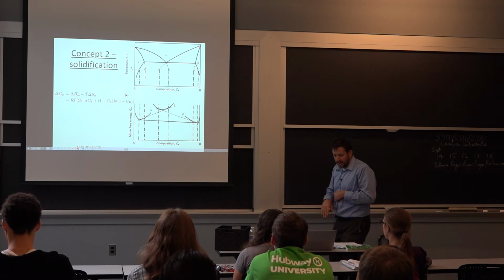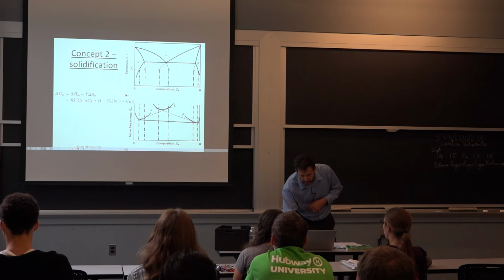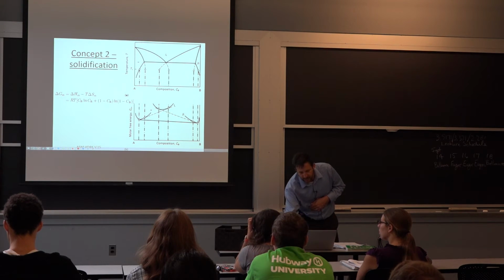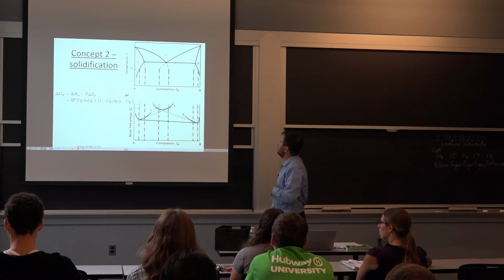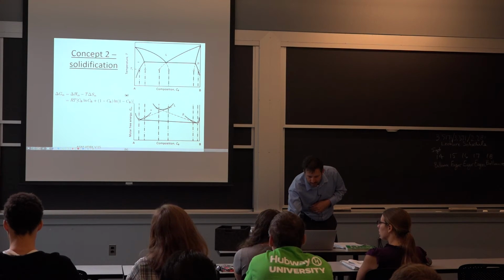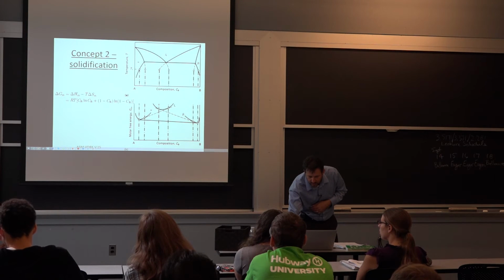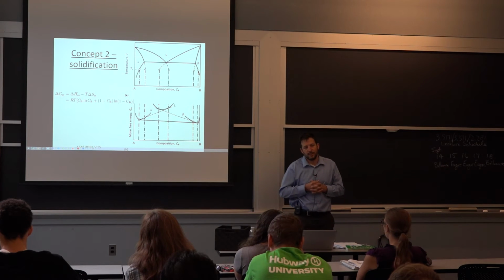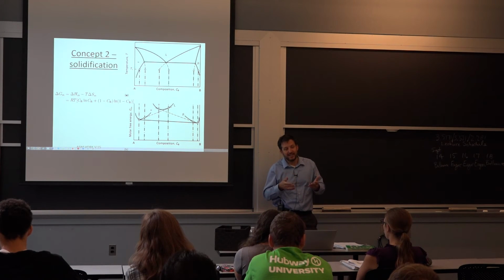And what really happens, you can see it from the diagram, is that at the beginning, this phase here, the aluminum phase in this example, doesn't want to take a whole lot of alloying element. And as you go further down, the alpha phase here does allow for more alloying element, but everything that started here with the pure aluminum leaves you with an excess of all these alloying elements.